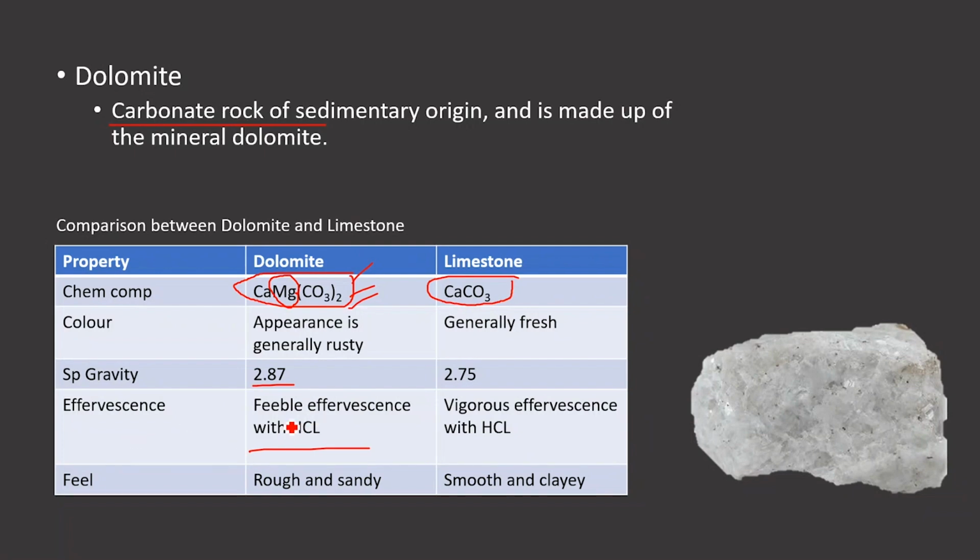The basic characteristics of limestone you must have studied in 12th science also. The test for calcium carbonate is to put a drop of acid on it. If calcium carbonate is present, it will create a brisk effervescence, so bubbles will come. That is a test to check whether it is calcite or not. That reaction would be very high in the case of limestone, which is properly CaCO3, whereas the effervescence will be very little in the case of dolomite. So that is a check.